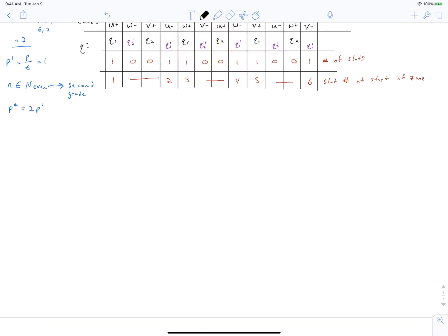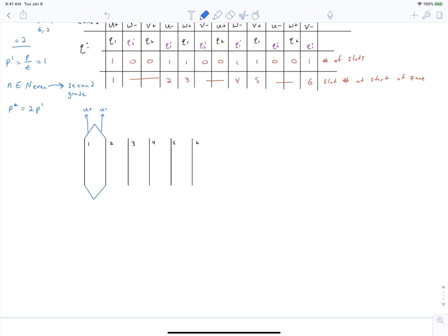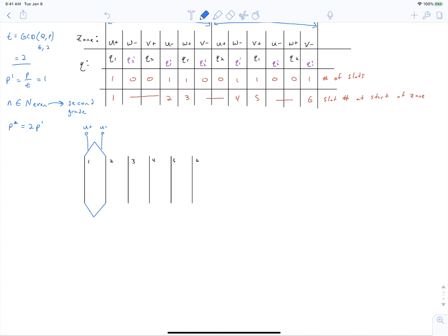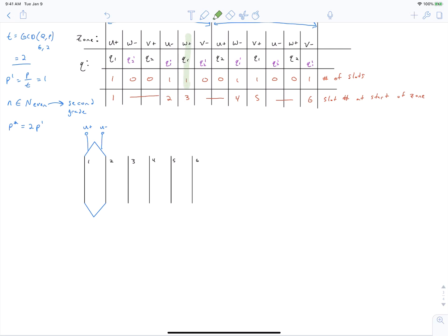So we'll do that quick, and we'll show all 3 phases this time. So first I've put a coil for phase U on here, and we can see that phase U has got slots 2 and 3, which is exactly what we've indicated for this coil. The next coil to consider is phase W, which occupies slots 3 and 4. And the next coil to consider is a coil for phase V, which occupies slots 5 and 6.